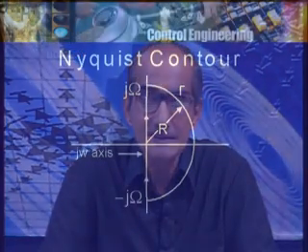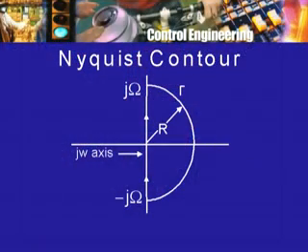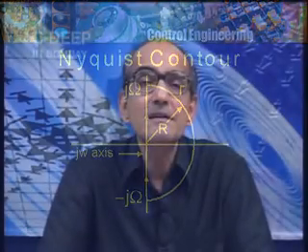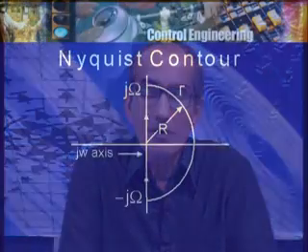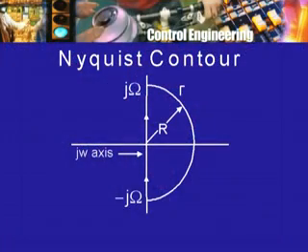Essentially what we have to consider is the situation that R keeps on increasing and then see what happens. Alright. So this is the reason for choosing the semicircle. The whole right half plane cannot be enclosed by a closed curve. It is not possible to do it, but any finite part of it can be enclosed by a closed curve like this, and therefore Nyquist chose the contour gamma in this fashion.